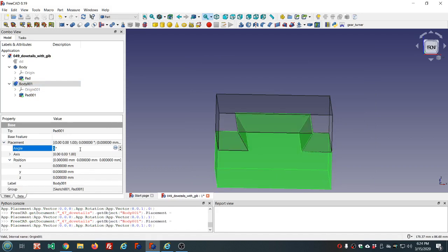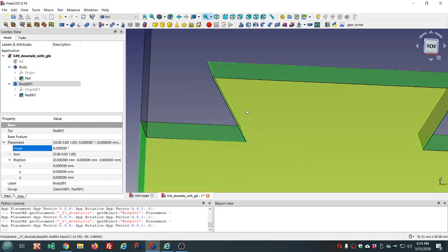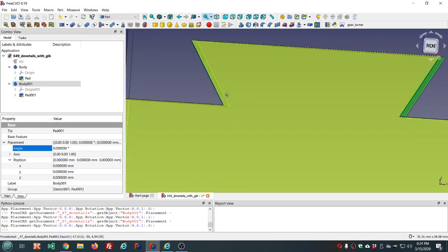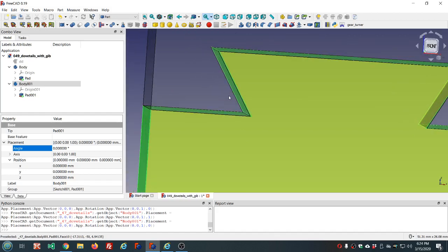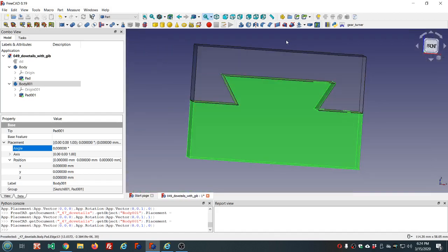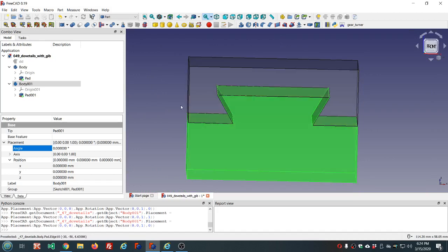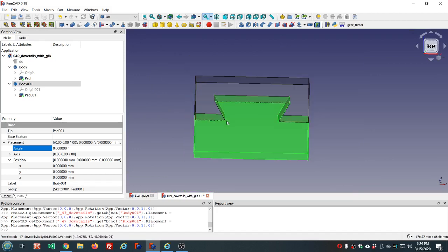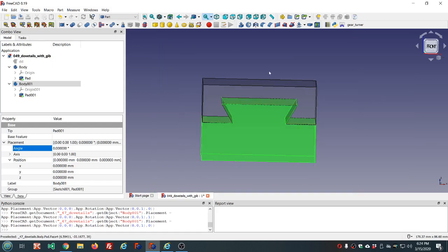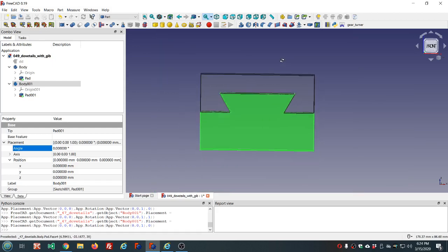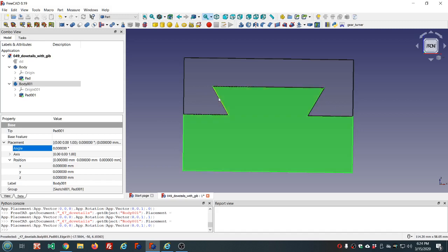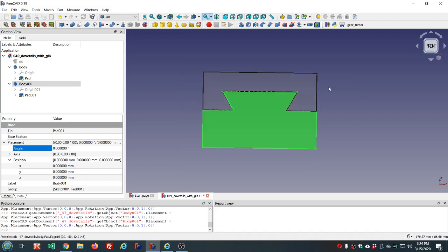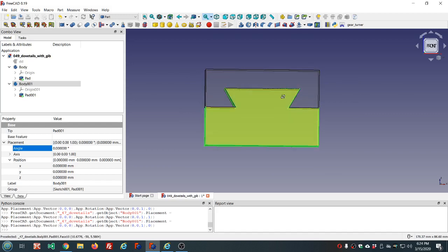If it's too loose, if the parts do not fit exactly well, you have a little wear maybe, you can adjust that out by tightening that gib up. So it lets you manufacture these not to the same exact tolerances and still be able to use them, and lets you keep using them after you get some wear in there.